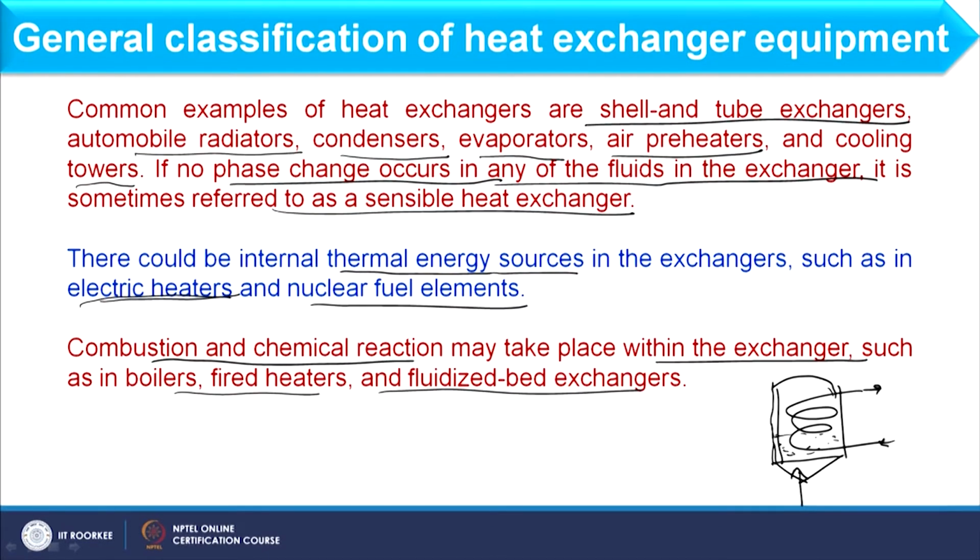When air comes in contact with the coal, it does two works. First, it fluidizes the bed, and second, it helps in combustion of the coal, because that occurs only in the presence of air. When this combustion occurs and the coal particles fluidize, they cover the complete coiling in which water is flowing, and then the water gets heated up. So that is basically the fluidized bed exchanger.